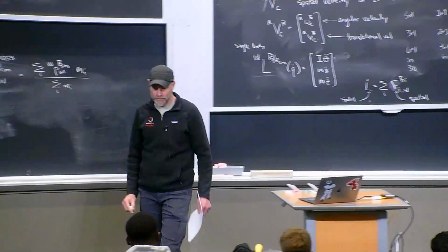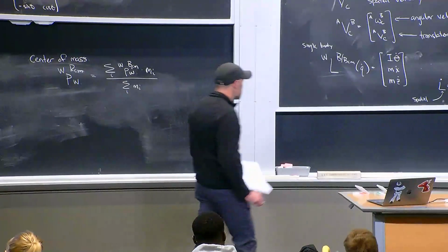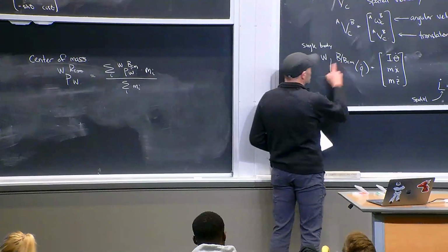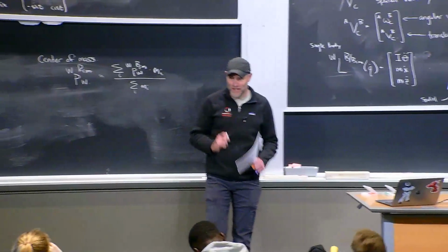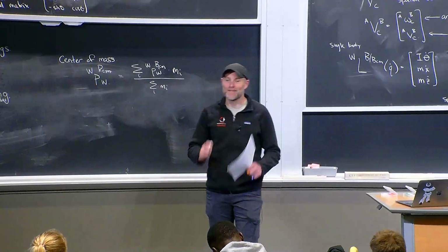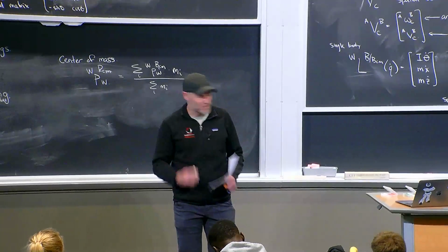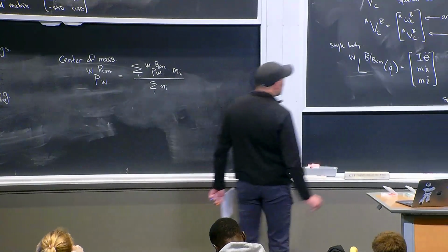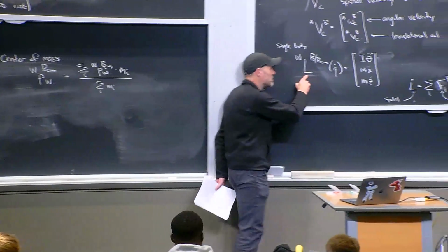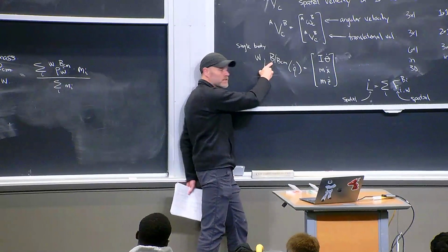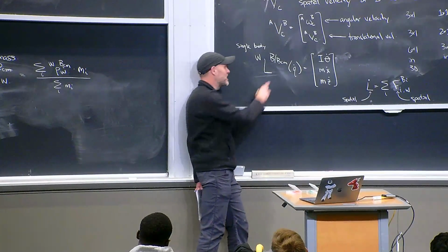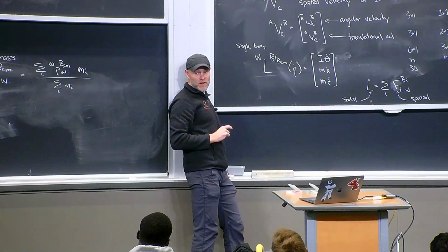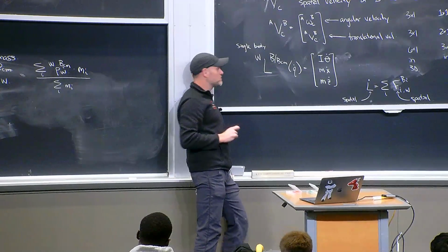Why do we write B/BCM? Yep. There's a surprising amount of work in the notation to make things clear in every possible case. And in this particular case, you need to say what you are taking the momentum of. It's the body B. And what point are you taking it about? You're taking it about the center of mass of body B.